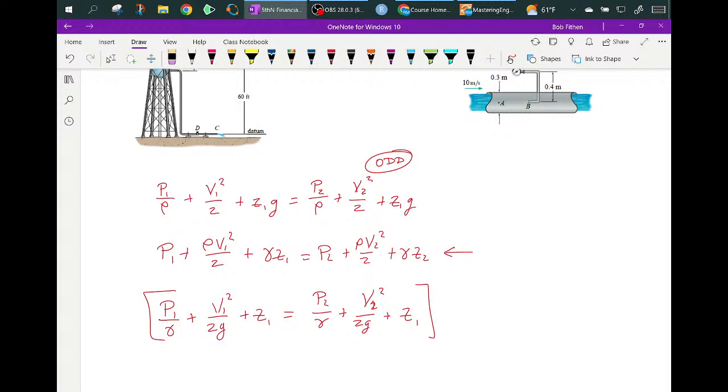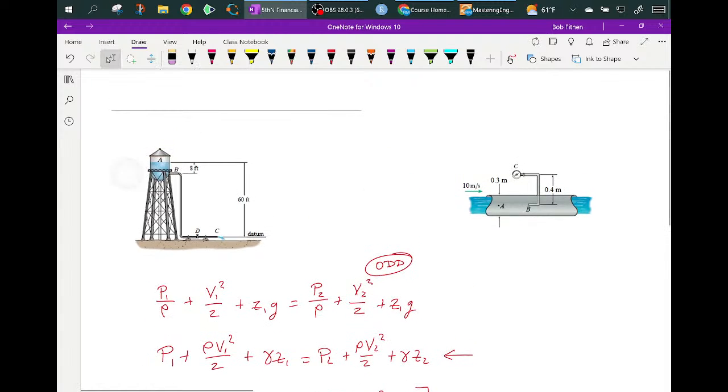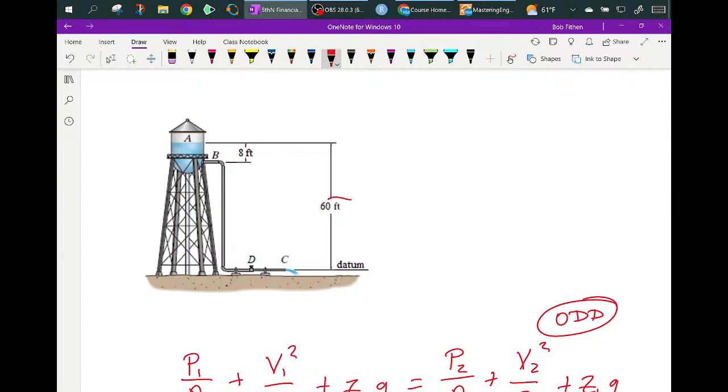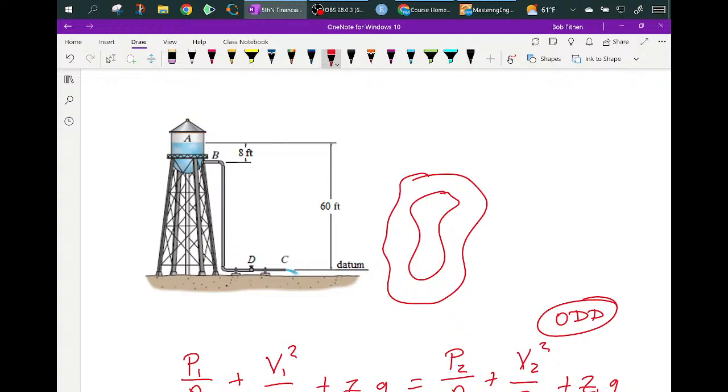Because you can look at it and say, hey, that has 60 foot of head right there, and that means this has 60 foot of head. So that 60 foot's coming out here. They can look at topology maps, at a mountain or a river, and if you're pulling water out of it, how high do you have to pump it up? Or how low is it going?